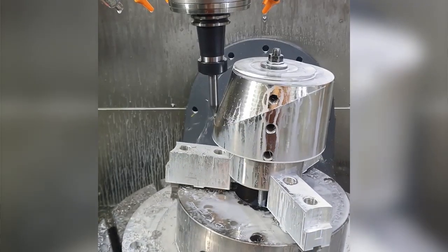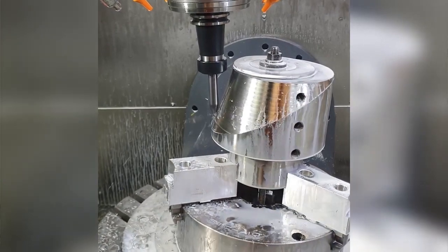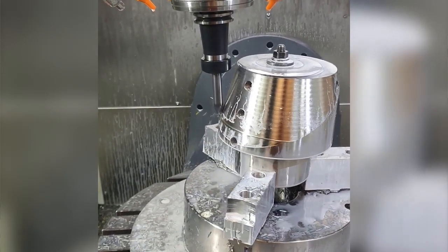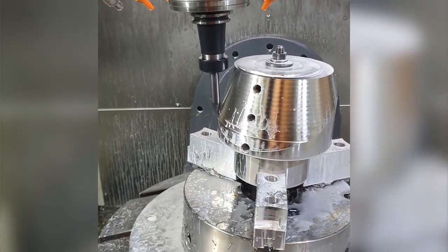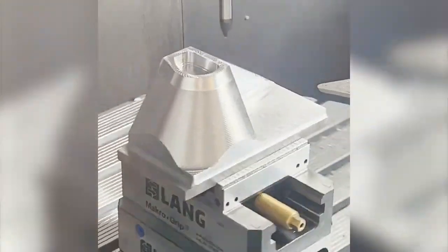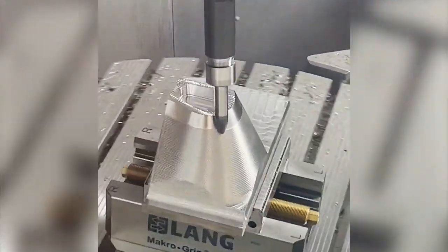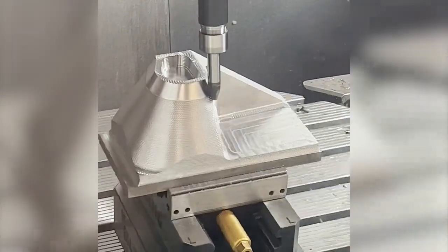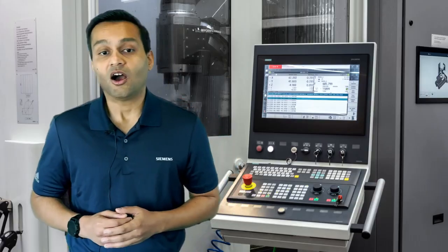In this machining example, we used a 3/4 of an inch barrel cutter to machine a conical surface with a zig tool path and simultaneous 5-axis non-cutting moves. By leveraging the larger contact radius of this taper barrel cutter, we were able to maximize the step over, resulting in a significantly shorter tool path. The reduction in machining cycle time amounted to an impressive 70%. Also, the surface finish was superior compared to using a ball end tool.